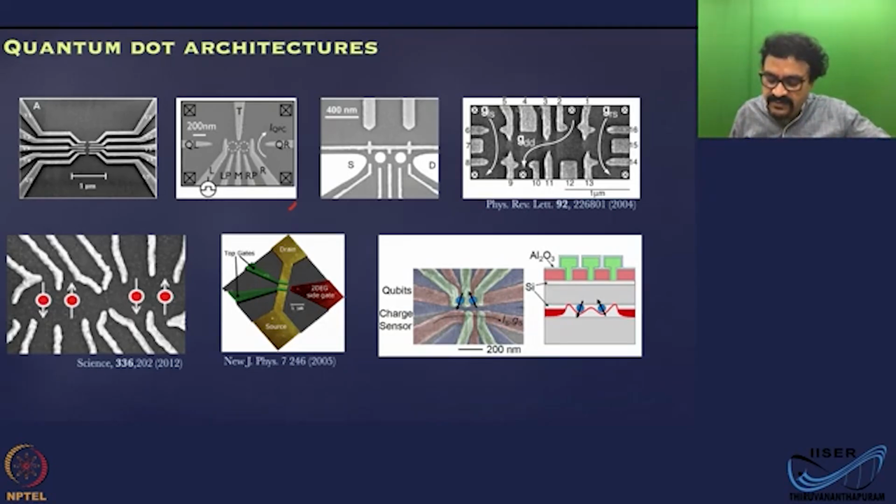So what you have is the red colored gates, which are enhancement gates, and the green colored ones are depletion ones. So you have two channels here. There are two red channels, one here, and this is going to host two dots, with these three barriers and two dots, and here you have two barriers and one dot. That is a larger dot that is for sensing. So you have two channels nearby. This channel will host the qubit and this channel will host the sensor.